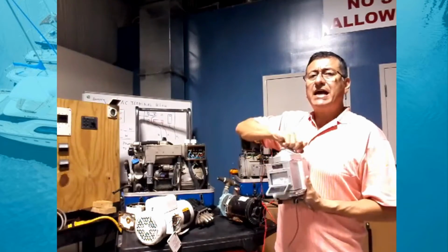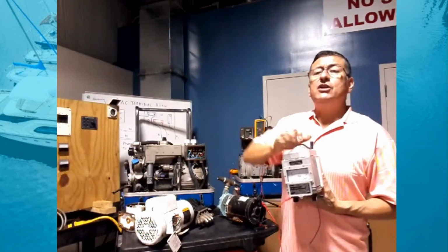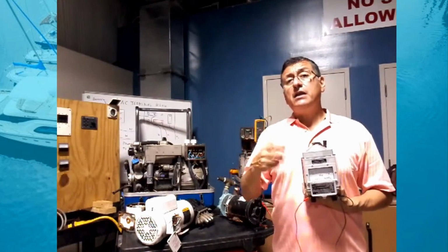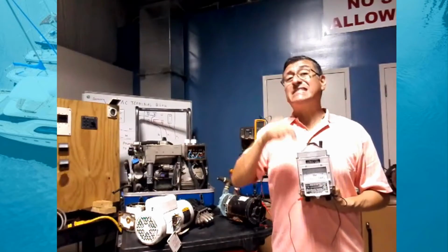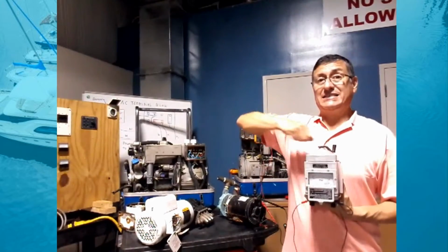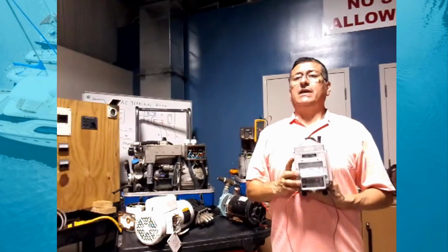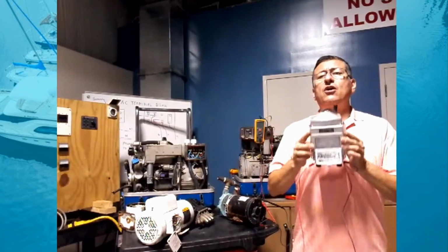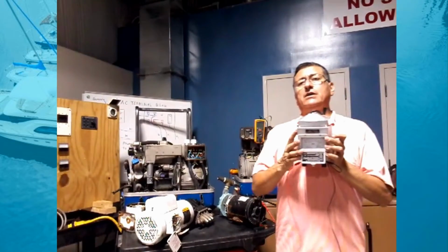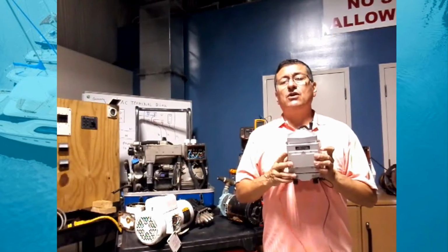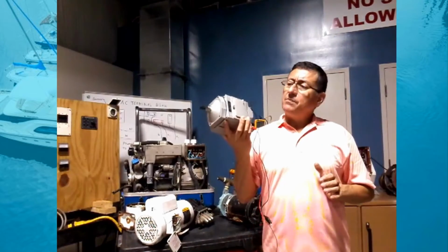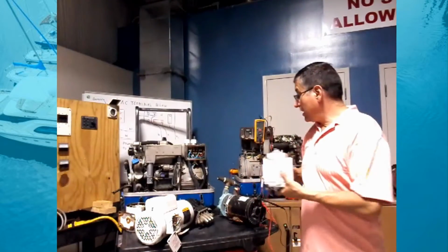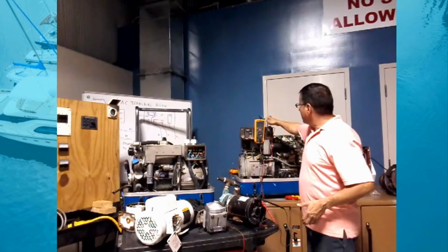When you crank this equipment here, you apply a high voltage on the winding. And with this equipment, you check how much is the resistance of that winding with that excessive voltage applied. This equipment is used to check the quality of the winding, to check the resistance on the winding. There are two types of megohmmeters. This one is completely mechanical, analog, and this one is digital.